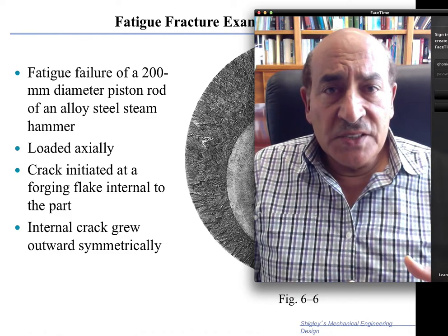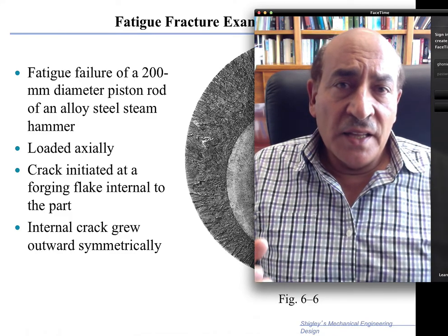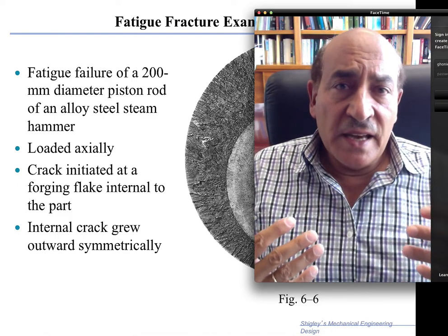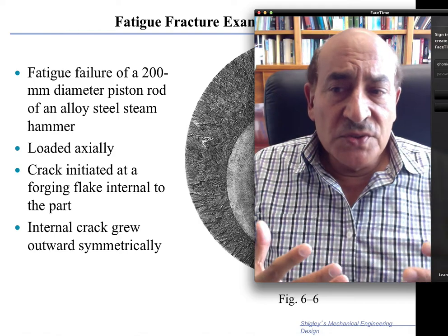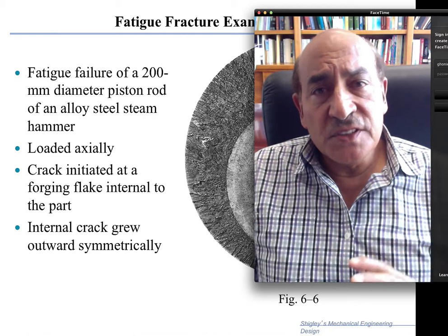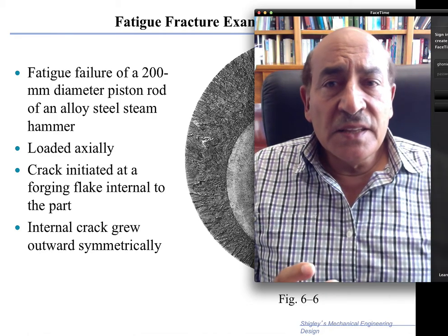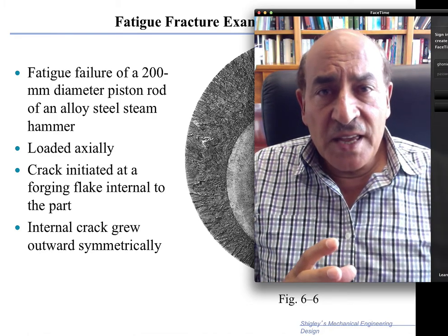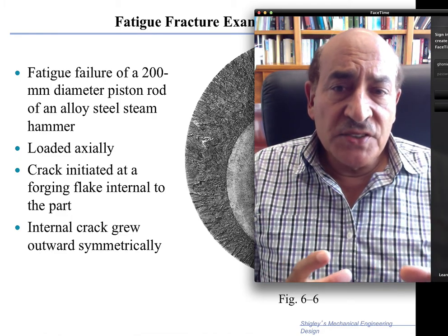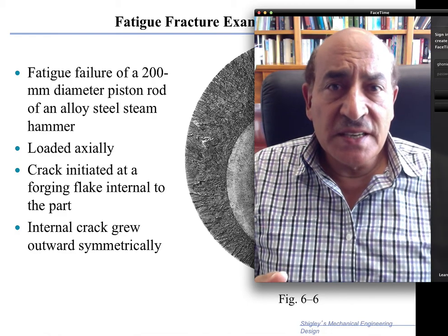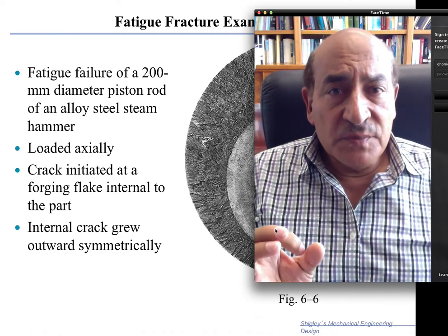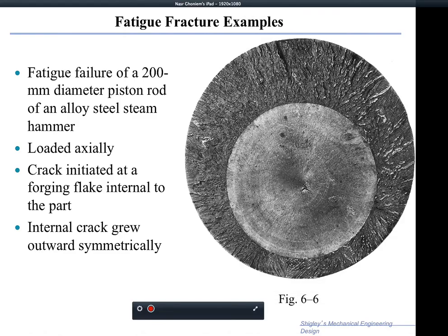Well, this example that I show is very interesting because the fatigue failure in fact started from inside the material outward. And how did it start? Because when you do some casting, the homogeneity of the material becomes different. So you might have some parts of the material that have different grains, or they have triple point junctions or stress concentrations at what you see here at the flake, and that will start the fatigue crack that could be small inside the material, and it looks like this.